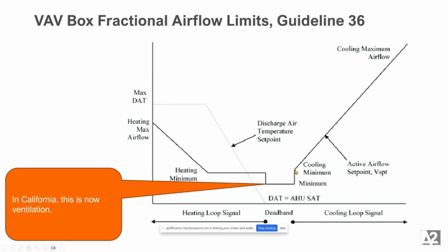And this might be, right, going down from cooling minimum, maybe down to ventilation in California. You could imagine if you then had DCV, there would be another number that it drops to when nobody's there, but you're still doing some flow for square footage. Or if it's a space that's allowed to go to zero, maybe it goes to zero. But then, right, the second you come out, you're in heating, boom, you hit this new heating minimum.